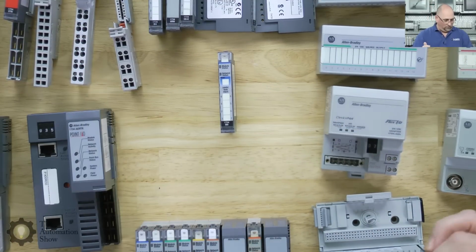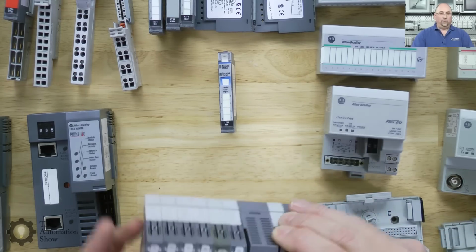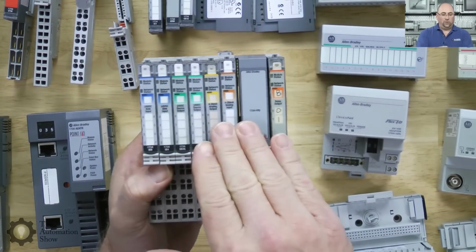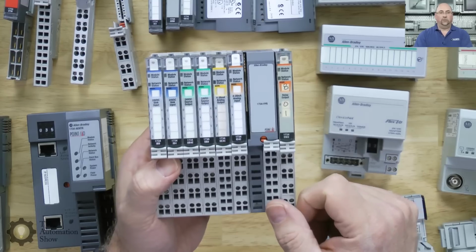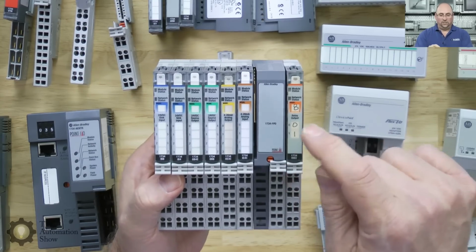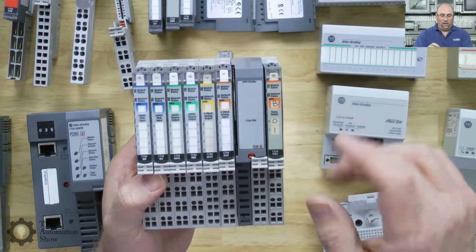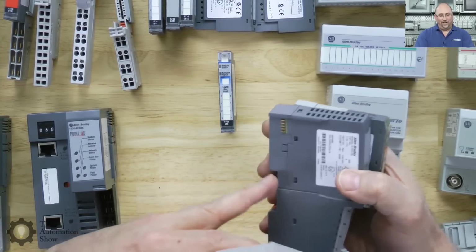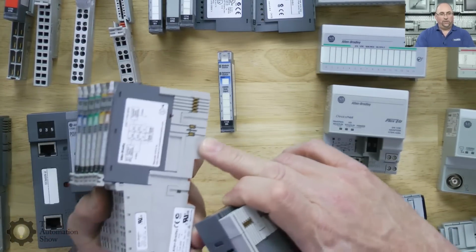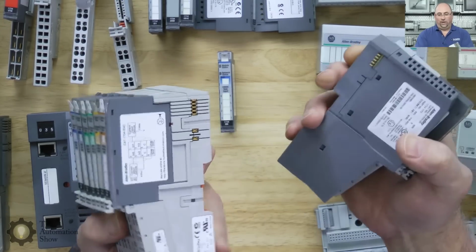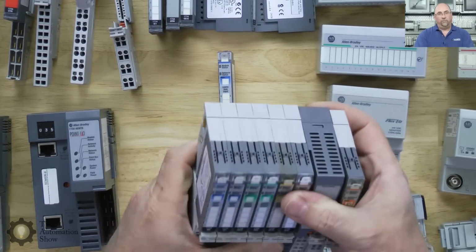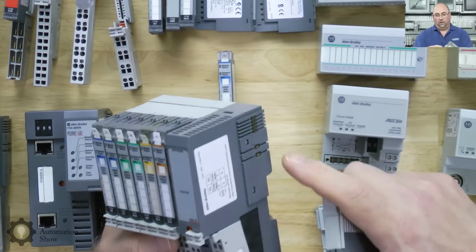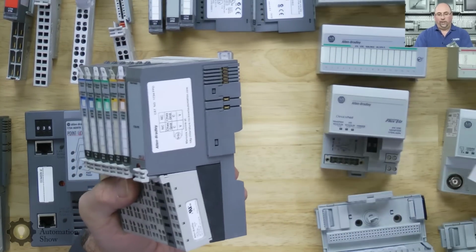You would need something. Where is it? Oh, here it is. You would need something like an FPD. So in this scenario, I'm using all DC, and then I wanted to use AC on this relay, so I have to put in an FPD, a field power distribution block. It breaks, you can see there's no power there. It's not even accepting the power pins from the left-hand side, because it's breaking the power of the field bus and allowing you to bring in, in this case, maybe AC, to go out to the modules on the right.